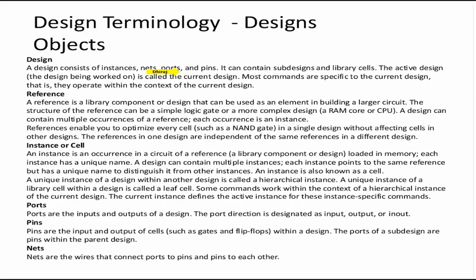So you want to set some design which you want to work on, you can use the parent design command. Let's say you want to query what all ports are there in the design. Most of such commands will work on the current design. They operate within the context of the current design. Reference is a library component or a design. So reference can also be used for a design that can be used as an element in building larger circuits. It can be a simple logic gate or a more complex design. One design can contain multiple occurrences of the reference, and each occurrence is called an instance.